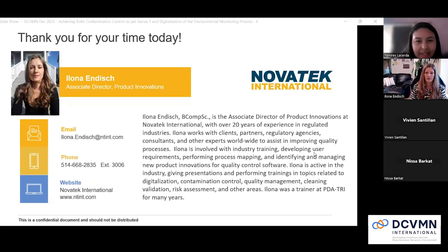Thank you. The next question from Pradeep, can the limit be established for trending? I don't know exactly what this means, but in the system, yes, because we didn't talk about the sampling plans really. In the system, you build sampling plans, you build all the tasks that you need to do with locations and your specifications, so you can establish the alert level, action level, and for water analysis or utilities, the minimum, maximum ranges. So all that is established, and you trend against that. That's how the system will know if there are excursions.